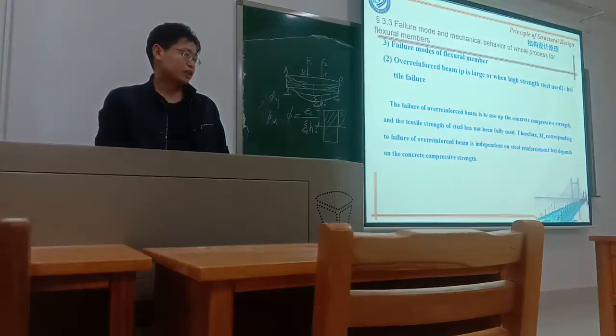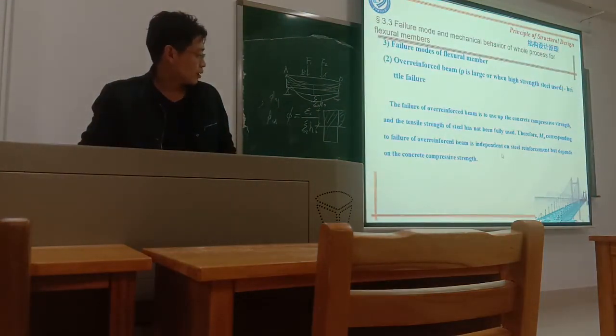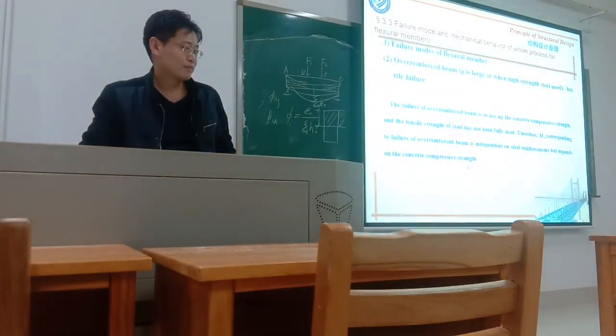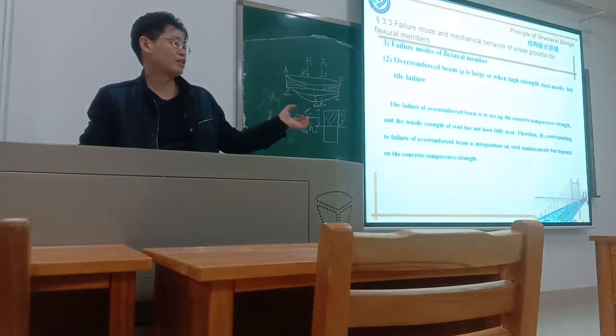So for this region, the load carrying capacity is dependent on the concrete strength. No matter what steel you use, because you put too much steel inside.